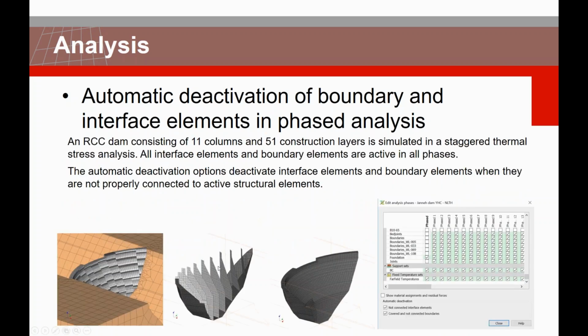As you can see here, there are some sort of interfaces between your cantilevers and you go through the sequence of construction stages, or when you want to go for a construction stage and you have young hardening, so you have a thermal boundary condition. So it's very important. You don't need to worry about the boundaries. You just select the active boundaries and elements, and when you deactivate them, the program automatically removes them.